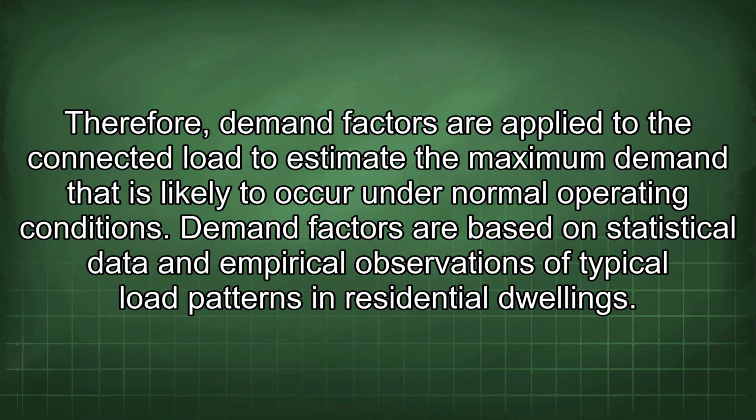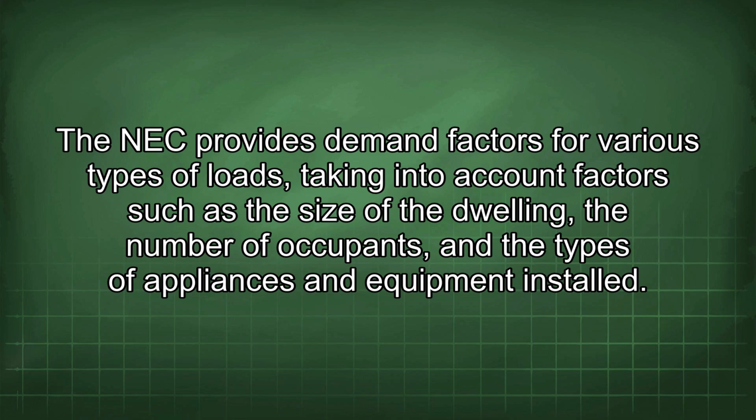Therefore, demand factors are applied to the connected load to estimate the maximum demand that is likely to occur under normal operating conditions. Demand factors are based on statistical data and empirical observations of typical load patterns in residential dwellings. The NEC provides demand factors for various types of loads, taking into account factors such as the size of the dwelling, the number of occupants, and the types of appliances and equipment installed.